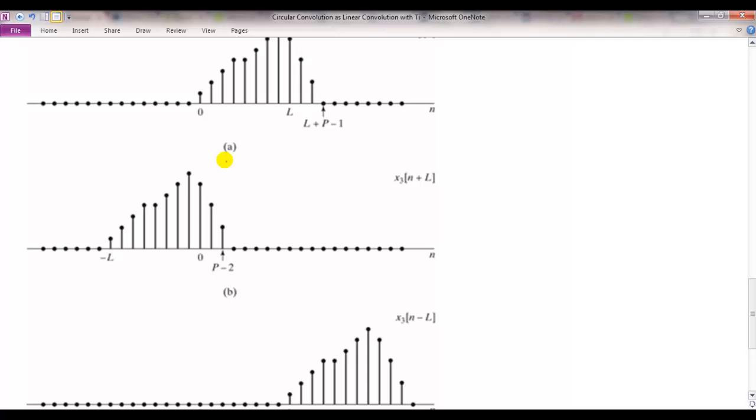And thinking of it that way also tells you when they will be both equal. And why do we care about this? Because in digital systems, especially in real-time systems, we hardly do convolution by writing the explicit convolution sum. We do it through the discrete Fourier transform, because the discrete Fourier transform has a much faster implementation. And if we do a discrete Fourier transform, then we are effectively doing circular convolution. So we better make sure that the answer of our circular convolution matches the linear convolution.